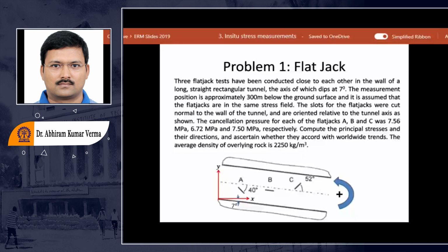At the place where the pillar of the bridge is standing, there is a separation happening, and you will see a lot of eddies getting formed over there, and the concentration of the water force applied on the bridge pillars is very high at those points. So this is the same concept when I'm making excavations below the surface.